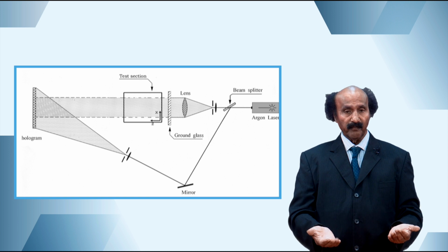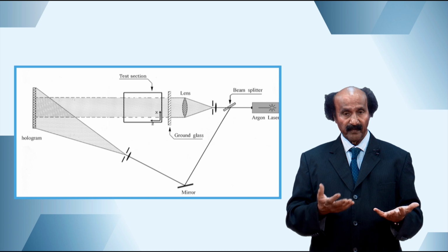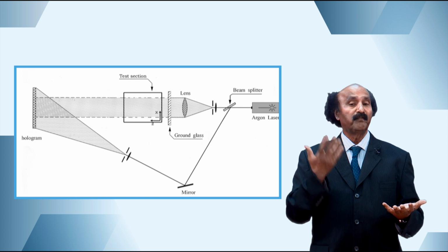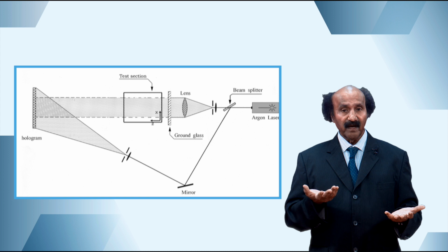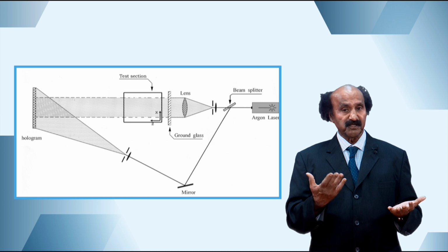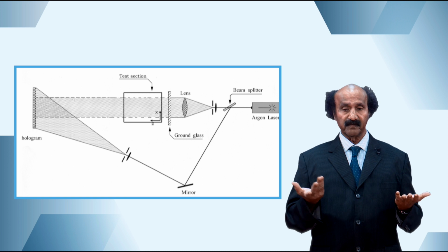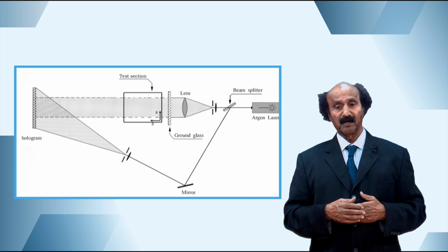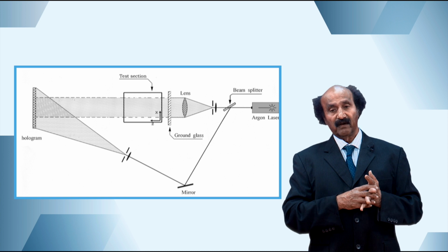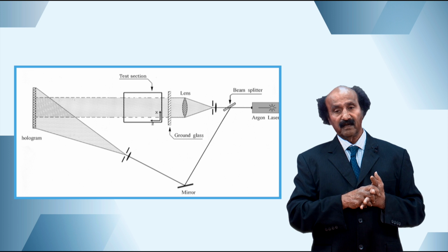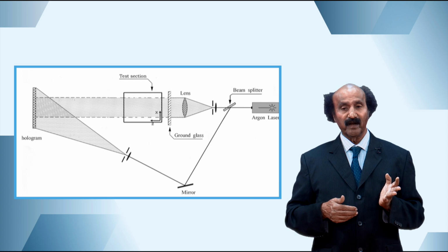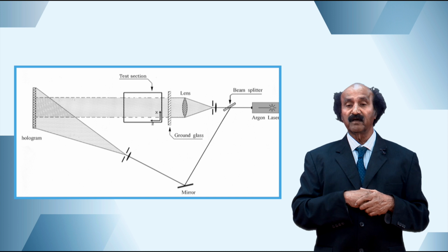Whereas in the bottom one, you take the same blade and allow it to vibrate. When it vibrates, you see the vibration at different frequencies, low frequency, high frequency. For example, in this example, the first one is vibrating at 983 hertz, the second one is vibrating at 2 times the frequency.